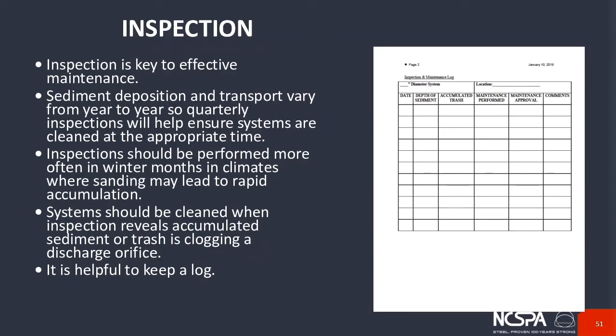So really the key to maintenance is inspection. You want to go in and make sure that you're not getting excessive sedimentation or debris gathering in the system on a pretty regular basis. But you do want to watch because from year to year, your sediment infiltration will vary.